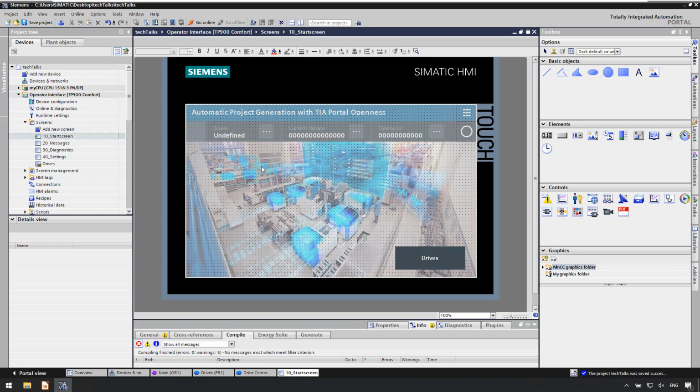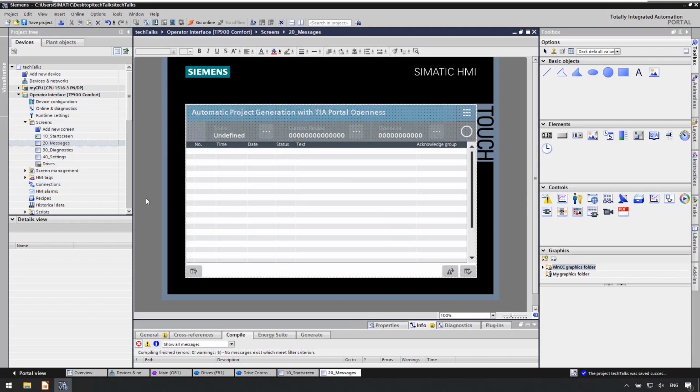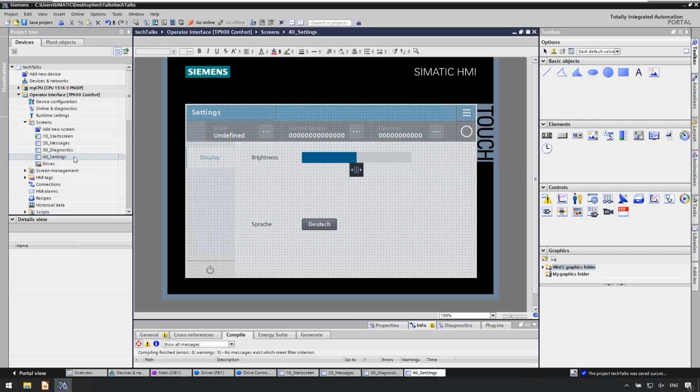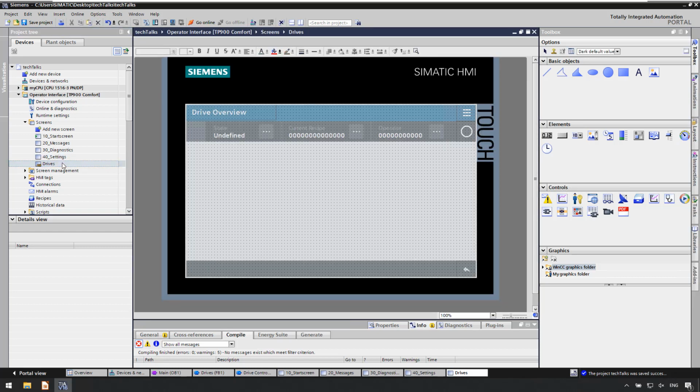So that's something that you can download directly from our support site and use in your project. That's just a library containing these templates, so they will drop automatically onto the PLC, onto the HMI. But what we also have is this drive screen, which, as you can see here, has a little icon saying SIV next to it. That's a SiVarc screen. But it's currently empty. It's empty because we now need to execute the SiVarc rules.